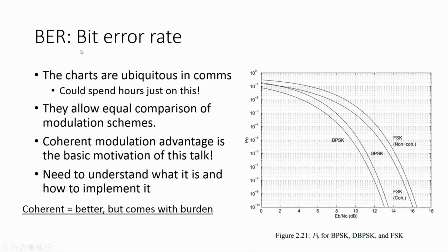Okay, the next thing that surrounds signal noise ratio is bit error rate, and that is if you send a certain number of bits, in this case again, we're going to normalize. If we send 1 bit, what's the probability of error? So in these bit error rate curves, the x-axis, the independent variable, is the energy per bit to the noise in 1 hertz bandwidth in decibels. So it's just a ratio. And if you sent 1 bit, what's the probability of that bit being an error? And these are decades. So here it would be 10%, and then 1/100th, and so forth.